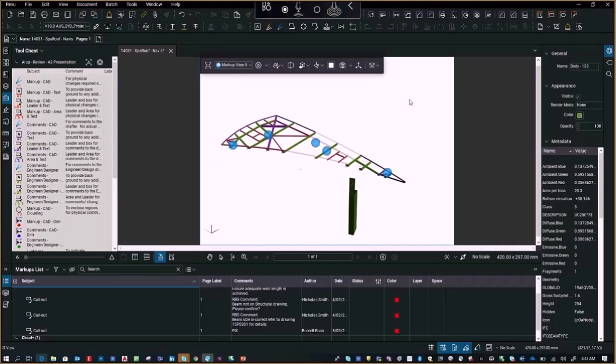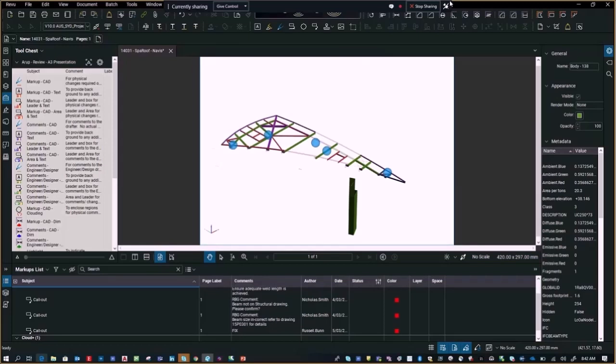So I was going to touch on some of the settings for the Revit and Navisworks export, because there are a few little things to be aware of. I was going to show it, but I can't go into Revit, so I'll explain. If you've got a section box in Revit and you export a 3D PDF using the Bluebeam plugin, the default setting uses that section box and exports that box as a 3D PDF with all the elements in it.